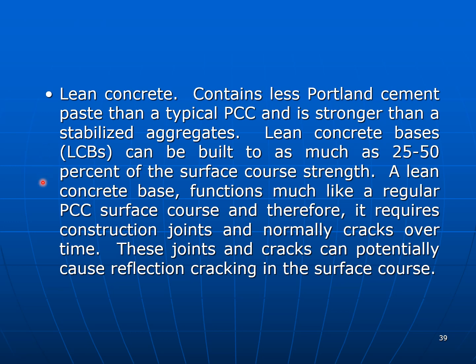A lean concrete base functions much like a regular PCC surface course, and therefore it requires construction joints and normally cracks over time. These joints and cracks can potentially cause reflection cracking in the surface course.